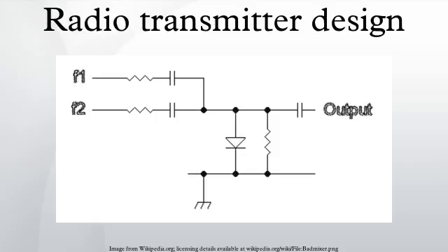Such RF devices are required by law to operate in an ISM band where interference to radio communications will not occur. Where communications is the object, one or more of the following methods of incorporating the desired signal into the radio wave is used. AM modes. When the amplitude of a radio frequency wave is varied in amplitude in a manner which follows the modulating signal, usually voice, video or data, we have amplitude modulation.